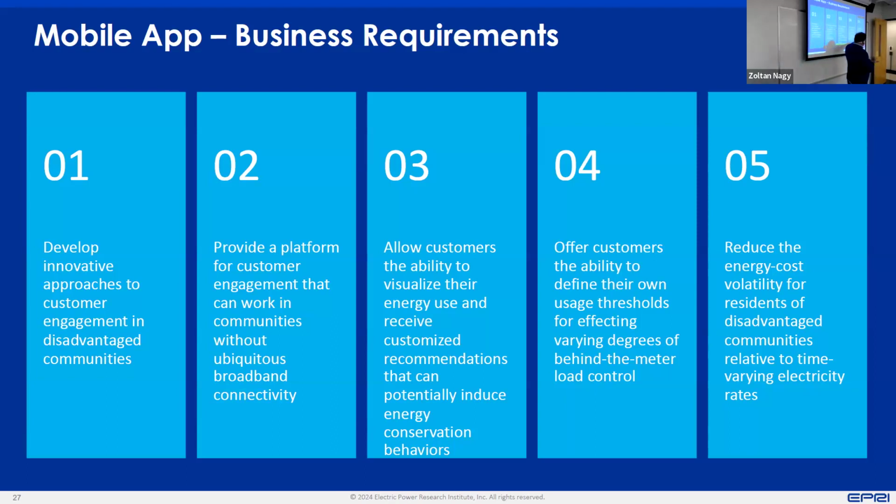Similarly, the energy cost volatility is important. And what does that mean? That means that one of your constrained control objectives is to make sure that the energy bill for the whole month doesn't exceed a certain dollar value. That's typically a challenging constraint, because it's not within the horizon of your MPC algorithm. It's not exercisable on every 5-minute basis. So there is a lot of challenge there.